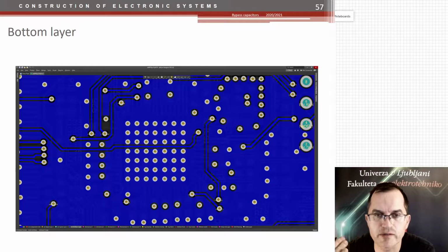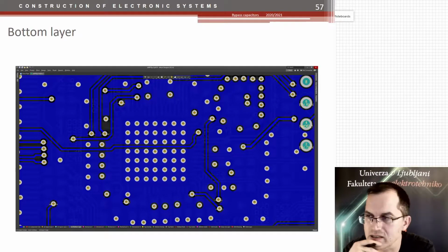More ground, well connected to each other, would make the impedance of the ground very low. That would first of all cause less common mode noise because of the current-generated common mode. But not just that, they would also decrease the loop sizes and the impedance for all the bypass capacitors you have.